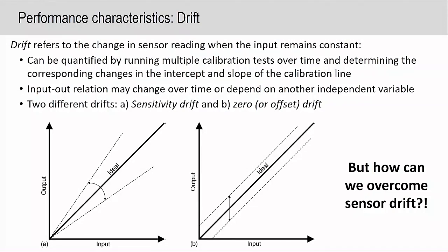Okay, so another idea that we might be able to do that we discussed up the back as well. The frequency of the drift may be different from the frequency of the signal. So you can build a filter to remove the drift and only leave the specific frequency of the signal. So, using signal conditioning essentially to overcome the problem. Yeah, software. Yep, absolutely.